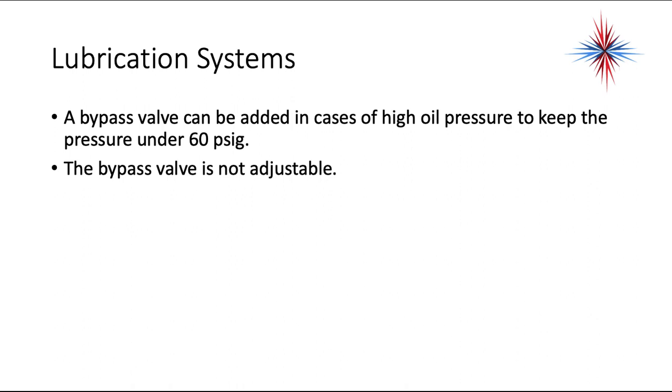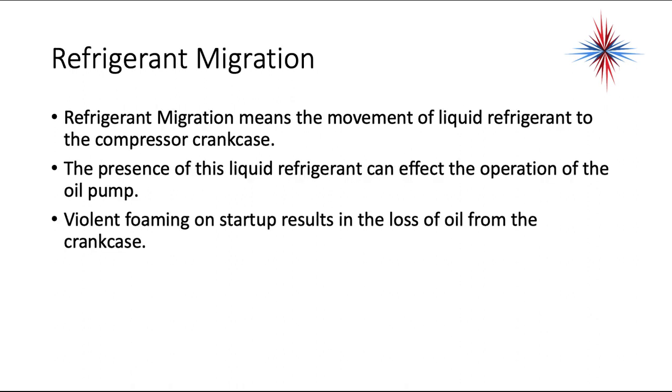A bypass valve can be added in case the oil pressure gets too high, to keep the pressure under 60 psi. Usually a bypass valve is not adjustable. We don't want that oil pressure getting too high because it can do damage.